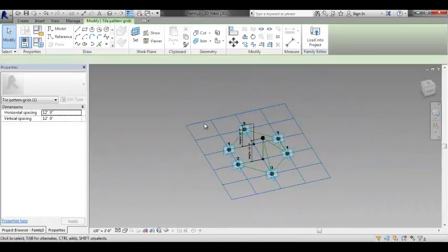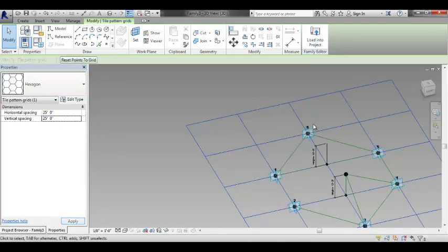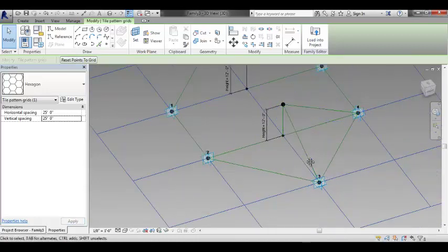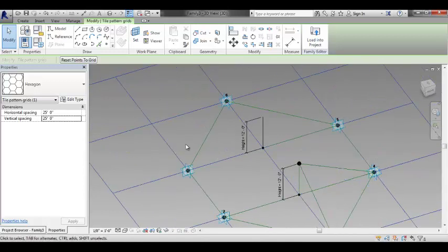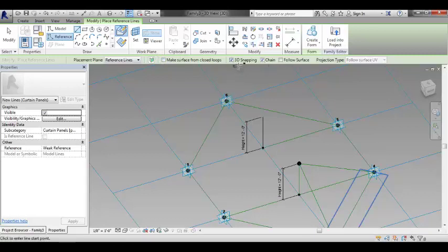But since I did make that move, at this point I'm going to flex the model again and just make sure that everything's snapping and staying snapped to it. And it is, so I'm okay with that. I already have a line here, so all I need is another line here, and I'll do the same thing on the other side. Then we'll just fill in geometry as if it's plane surfaces. So I don't really need that on anymore. On this one I'll make sure 3D snapping's on. In this case I'm going to go from 1 to the end point, to the side,